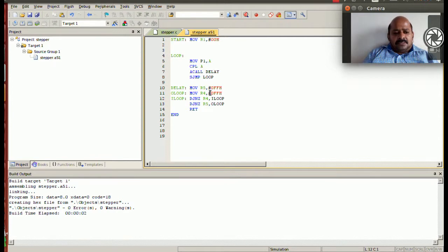Okay, so let us consider 12 samples in a waveform. If we consider 12 samples for the entire period, then each of the samples are separated by a distance of 30 degree, because 12 samples correspond to 360 degree. So two of the samples are spaced at a distance of 360 divided by 12, that is 30 degree.